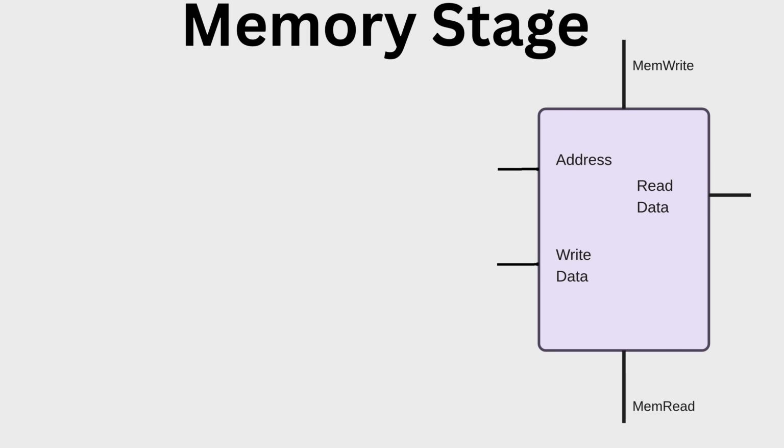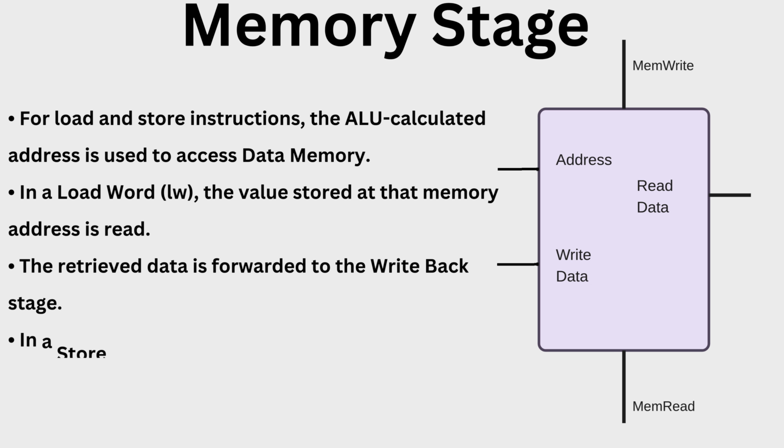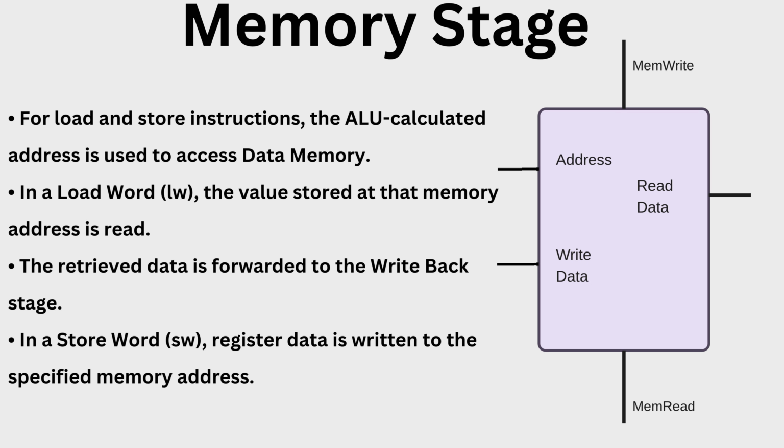Next comes the memory stage. For an ADD instruction, no memory access is required. Instructions such as load word and store word would interact with data memory during this stage, but arithmetic instructions simply pass their result forward unchanged.